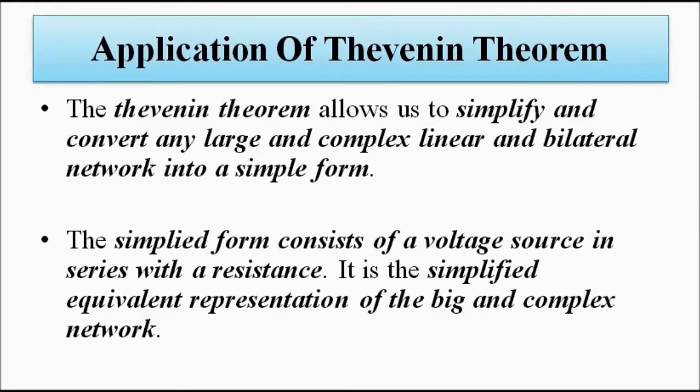So what Thevenin theorem does is that it converts a large circuit, be it any number of voltage sources, 3, 4, 5, 6 current sources, whatever number of resistors, into a simplified form which consists of a voltage source, called the Thevenin equivalent voltage. Okay, we'll come to that.